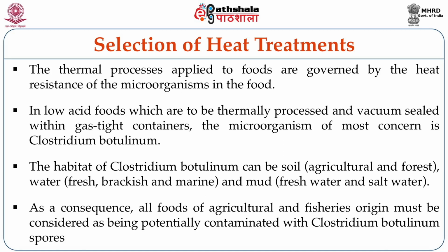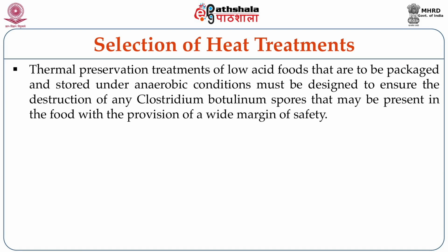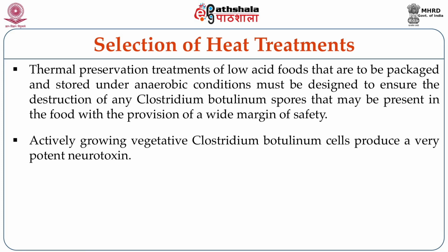So, the habitat of Clostridium botulinum, which can be soil or water or mud, has to be taken into consideration. As a consequence, all the foods of agricultural and fisheries origin must be considered as being potentially contaminated with Clostridium botulinum spores. Thermal preservation treatments of low acid foods that are to be packaged and stored under anaerobic conditions must be designed to ensure the destruction of any Clostridium botulinum spores that may be present in the food, with the provision of a wide margin of safety. Actively growing vegetative Clostridium botulinum cells produce a very potent neurotoxin.